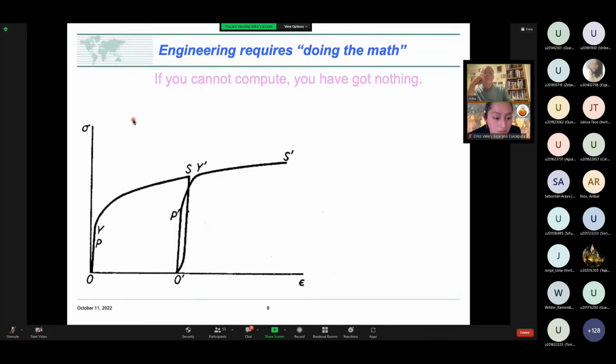Before I get into finite element analysis, I've got to tell you a little about soil behavior and how we represent it, because that's what we need in finite element analysis. What I've put on the screen here is the sort of thing you might measure in a triaxial test. We're loading up a deviatoric stress here, and measuring axial strain here. If we keep loading up to this point and then unload, you'll find you get virtually none of the displacement back.